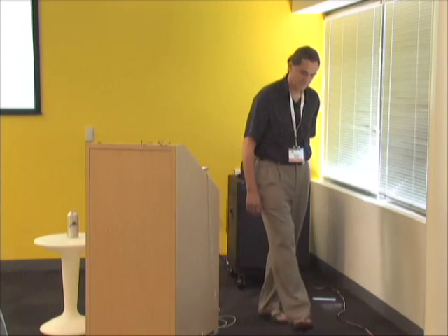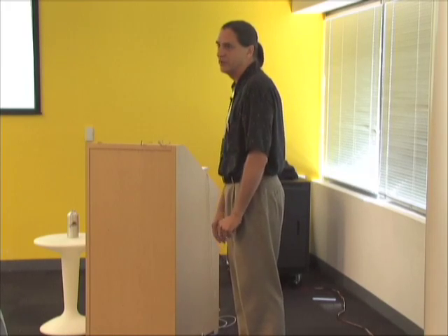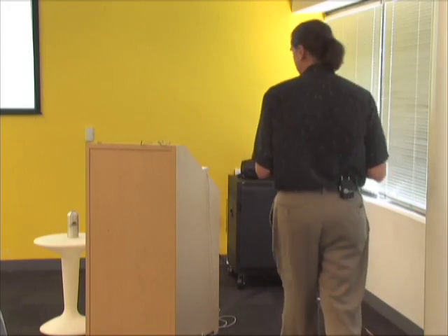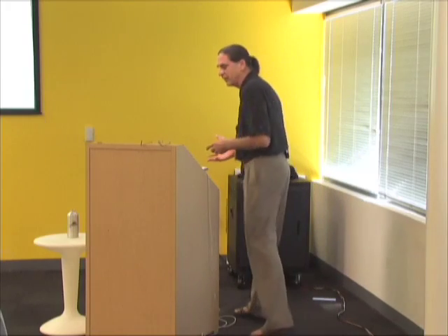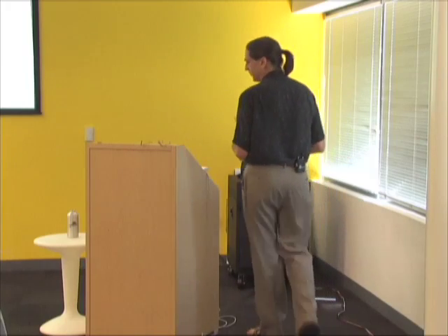Layers. The important thing about using layers is layer 0 is a very special layer. My recommendation to everybody is you should model on layer 0. You should group at whatever level you think is important things into groups or components, and then you should put those on named layers. And named layers that you understand the names of and you can sort through and find. My models sometimes have 400 layers and they're very organized. We often organize them by process. All our structural elements will have an S in the front because I get tired of looking for girts and purlins and beams and columns and all sorts of different places. I want them all together because I like to go through them and highlight them and turn them all off at once. It's just trying to be organized.